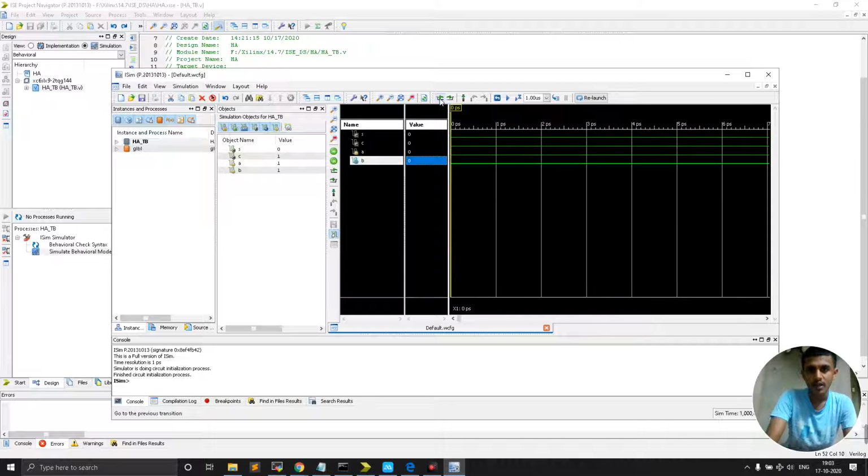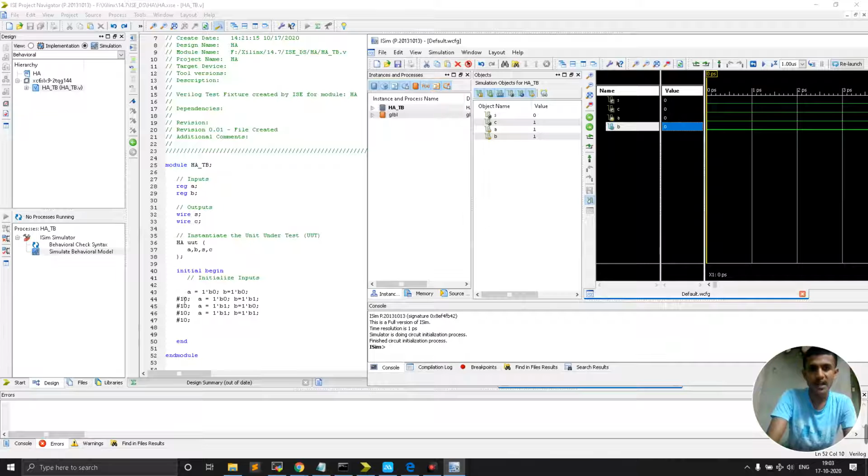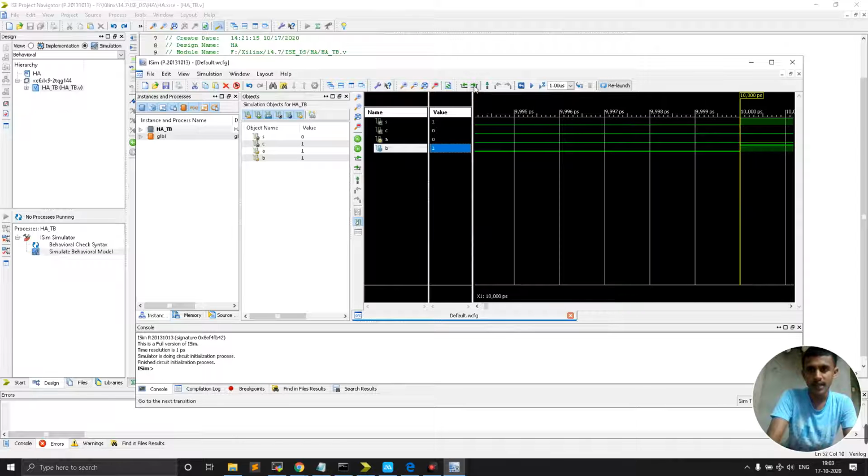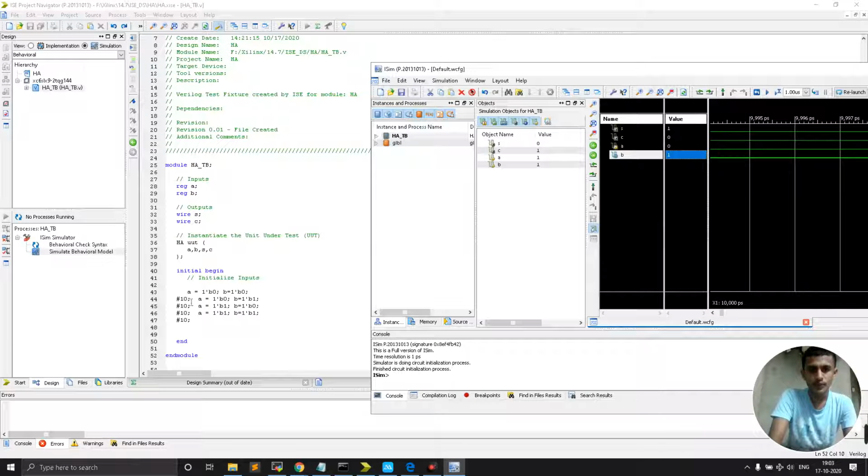Instead of that, what we do is just click here. Now, how much delay do we give here? It is just 10, so here we have to check. I think it's going to be 10 picoseconds. If I say millisecond or microsecond, that's wrong. It has to be in picoseconds. In previous videos, 10 picoseconds. So how much time do we need? 10 picosecond plus 10 plus 10 plus 10, 40 picoseconds is enough. That much runtime is enough.